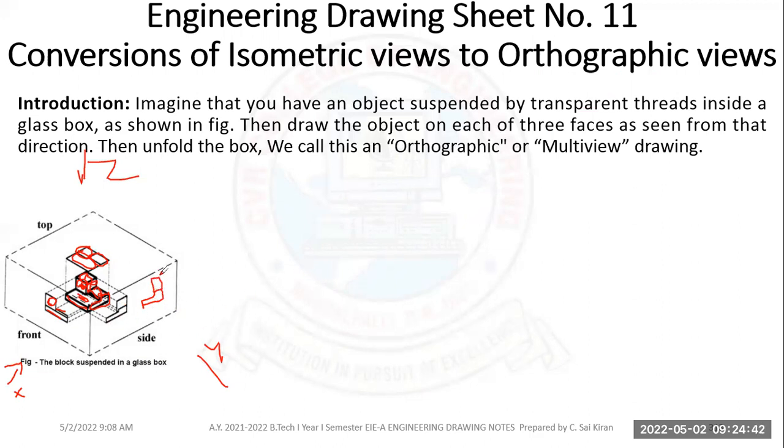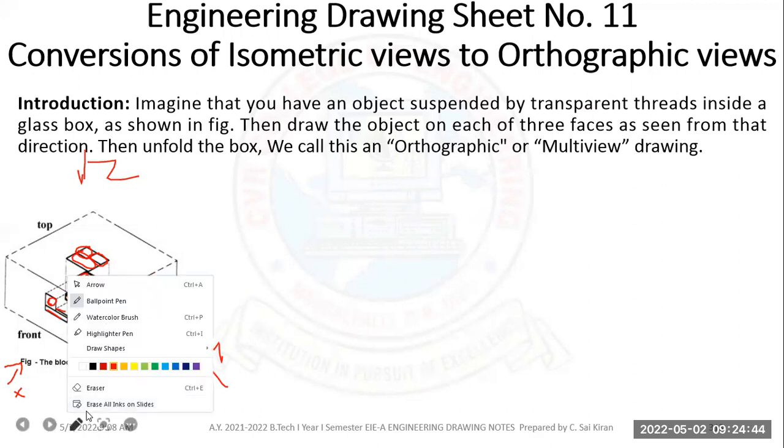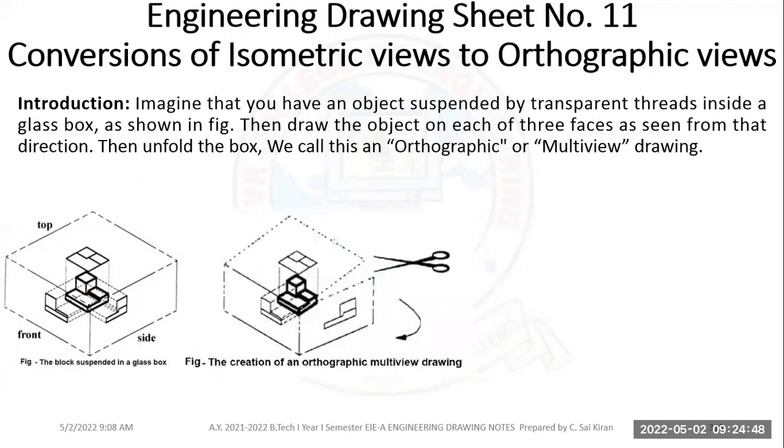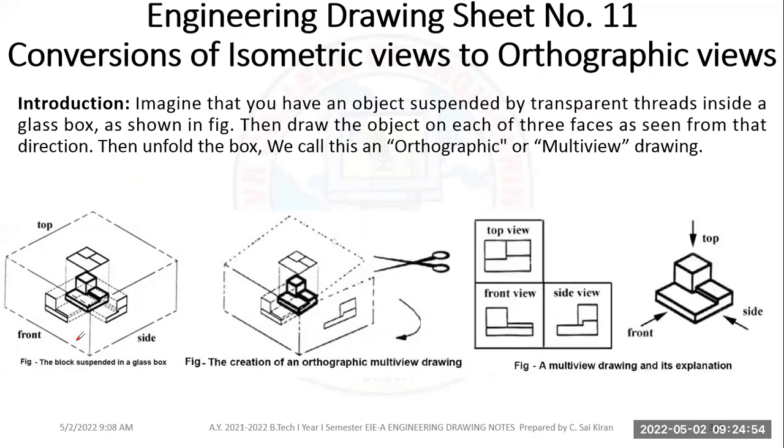Okay. And this I took from an American PPT. So it will show as a third angle projection. Then we are making the projections because it is a third angle projection. They use third angle projection. That's the reason top view will be above and front view is down, and beside the front view it has the side view.